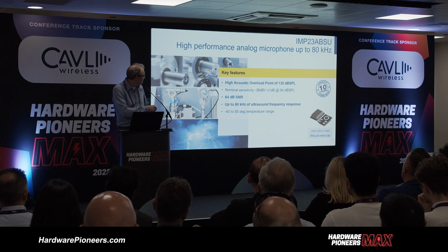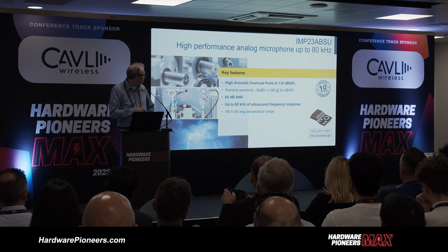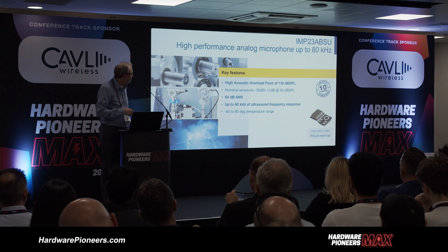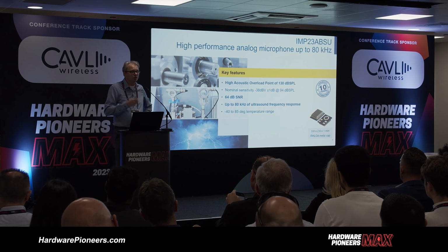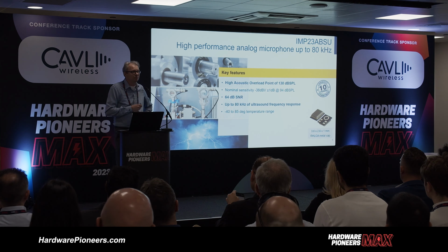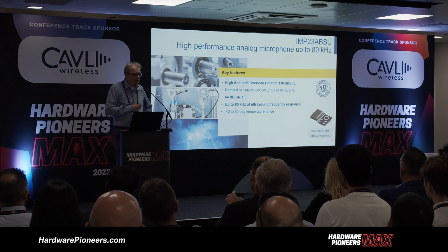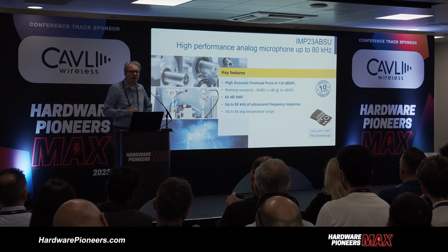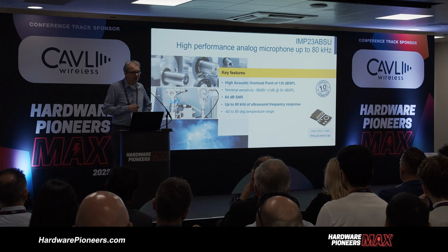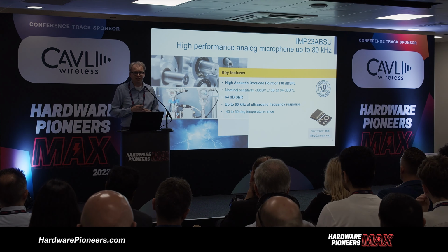And one of the key merits is the signal to noise ratio of this component. You can see the applications here: different kinds of motors, especially if you have gearboxes and bearings, these start to generate artifacts in ultrasound. But also anything related to gases, so pneumatic systems. If you have a gas leakage, this will produce ultrasound. And then the last one here, anything related to electricity, electric shocks and pulses. Creating spikes is what also creates ultrasound.